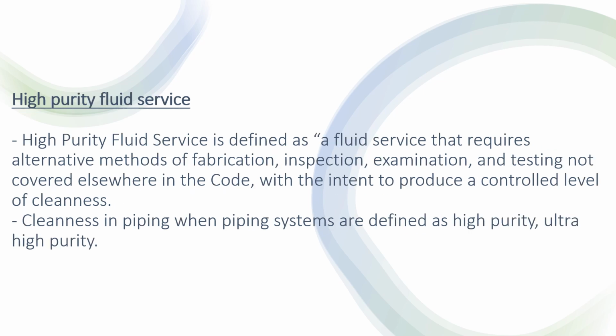Then we can go for the high purity fluid service. High purity fluid service is defined as a fluid service that requires alternative methods of fabrication, inspection, examination and testing not covered elsewhere in the code, with the intent of producing a controlled level of cleanness. Cleanness in piping, when piping systems are defined as high purity, ultra high purity. What is high purity fluid service? I have to explain.